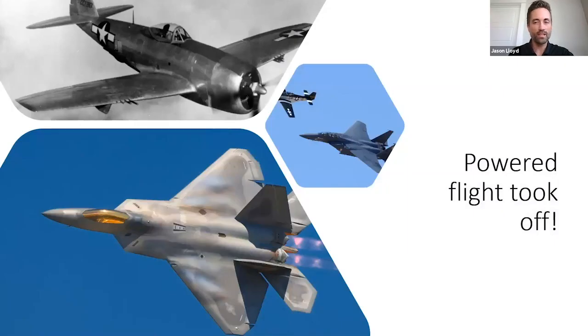So if we set aside the redundancy of the wings for just a second, powered monoplanes had the advantage over the multi-wing planes of reduced drag by eliminating the exposed bracing between wings and internally carrying all of those wing forces. The monoplane had superior aerodynamic efficiency, allowing faster flight, but also required higher powered engines to fly the heavier frames.